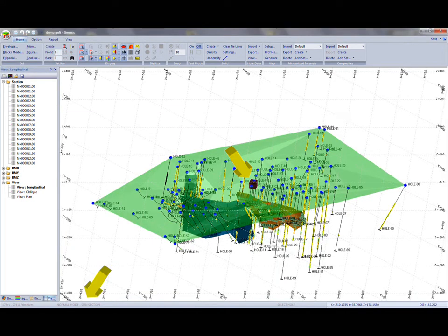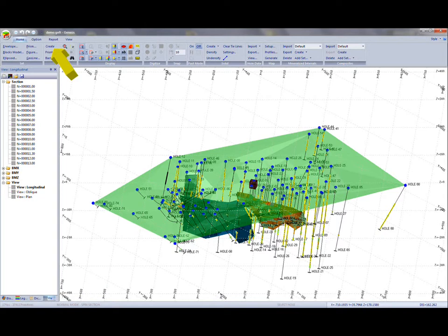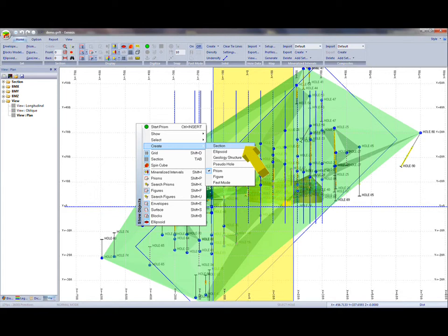Section creation during rotation mode. When you are in spin mode, it is possible to create a section from your current view. The anchor point corresponds to the center of rotation, which is a small red textured cube in the center of the screen. The angle will be determined as a function of the current view. Simply click on the Create button in the section menu.